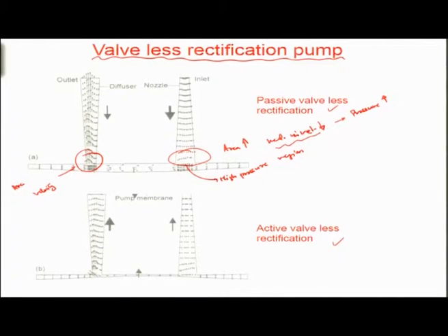So area here is lower and velocity is increased because of that, and therefore the pressure is reduced, and so the pressure at this point right here would be lower in comparison to point A. Let's say this is B, and this is A. So lower in pressure than the pressure at A.